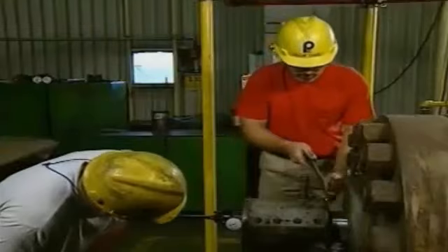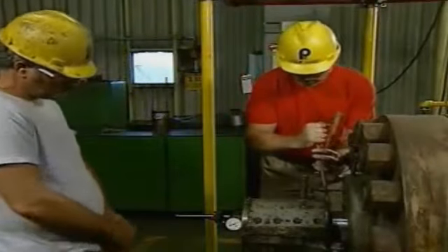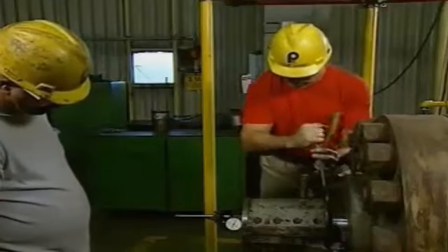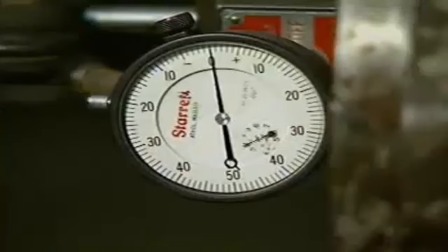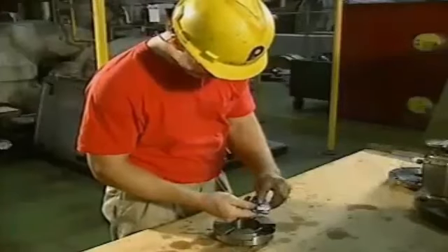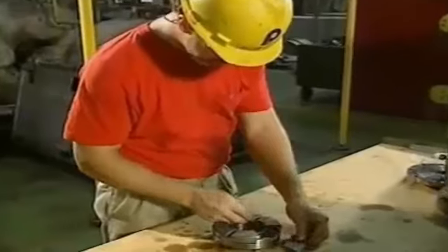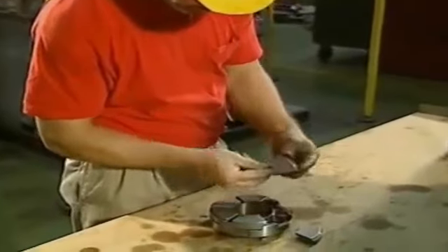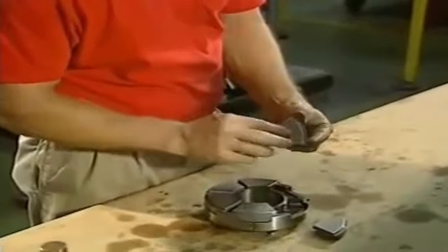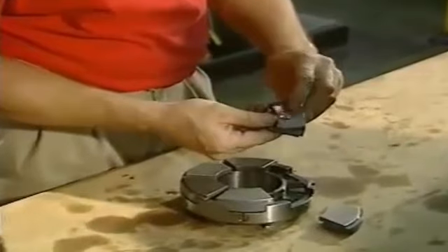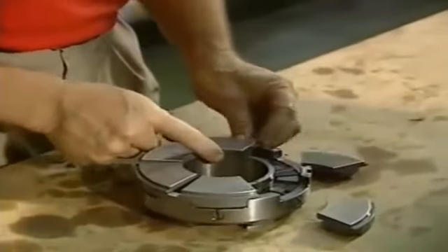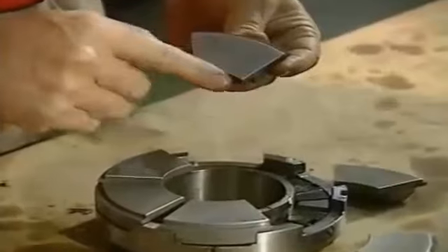To check the reading, the mechanic moves the shaft back in the other direction to see if the dial indicator returns to 0. If the dial indicator does not return to 0, the indicator may have slipped and the reading should be taken again. Worn-out thrust shoes are a common cause of excessive clearance in a thrust bearing. However, the only way to determine the exact cause of the excessive clearance is to disassemble the bearing and inspect the shoes.